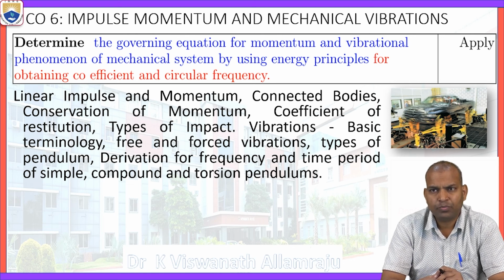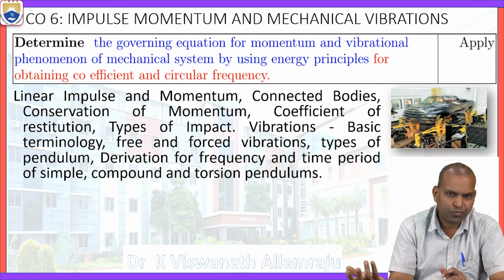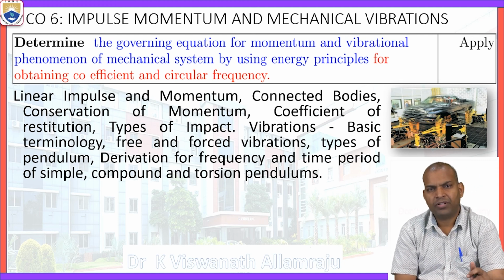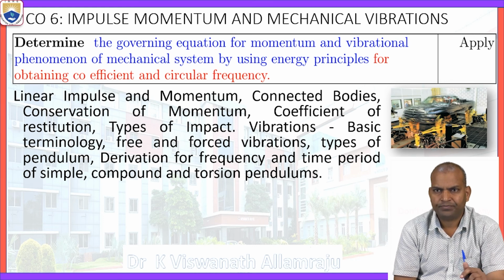For that, we have to use these vibration testings, to see whether the machine is able to withstand those dynamic forces or not. If it is not, then we have to go for redesigning it. After that, we have to verify it, rectify it, and again fabricate.